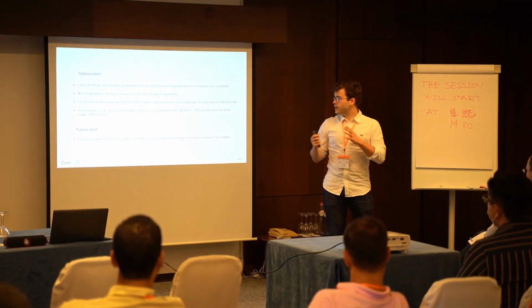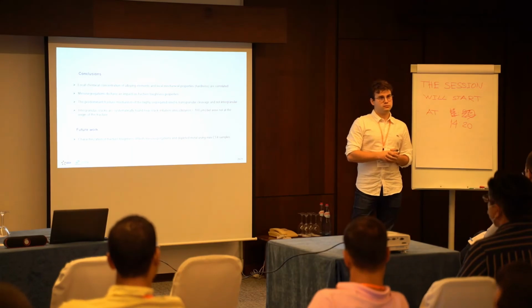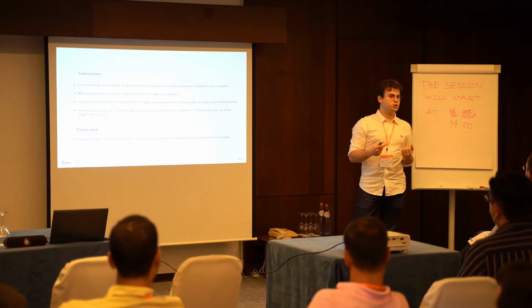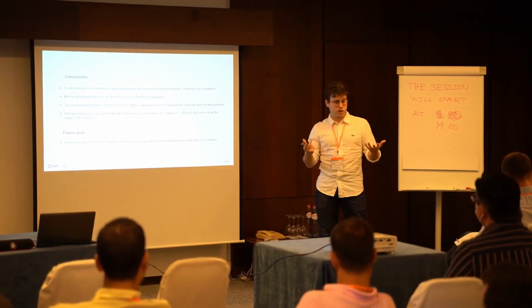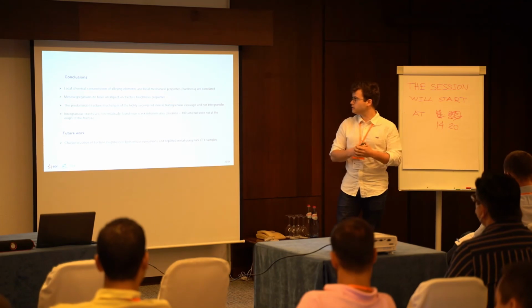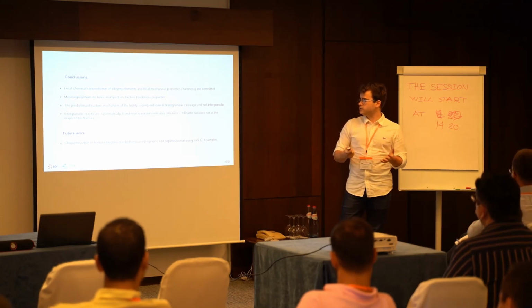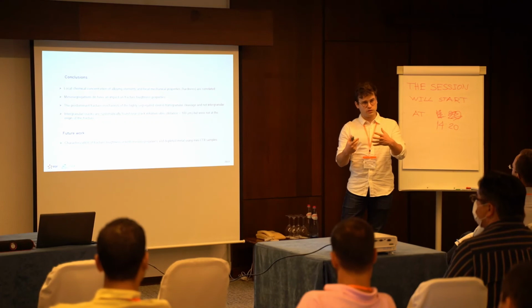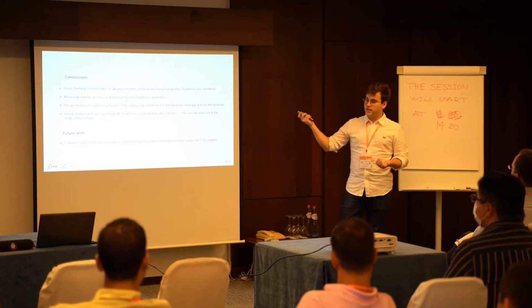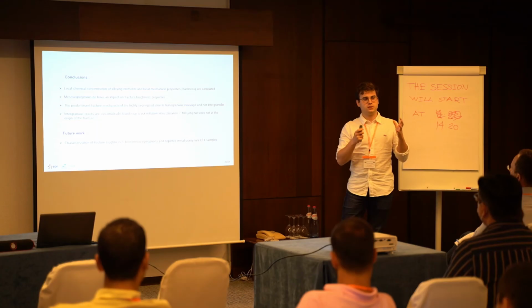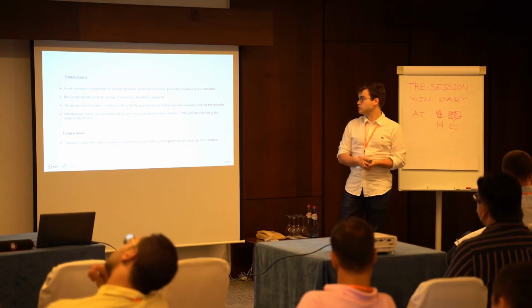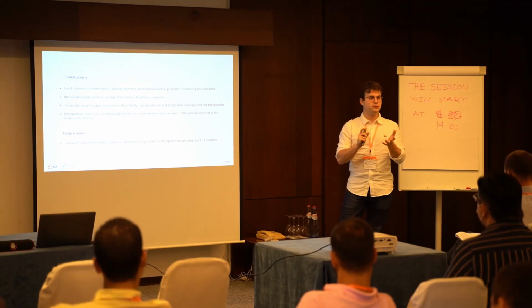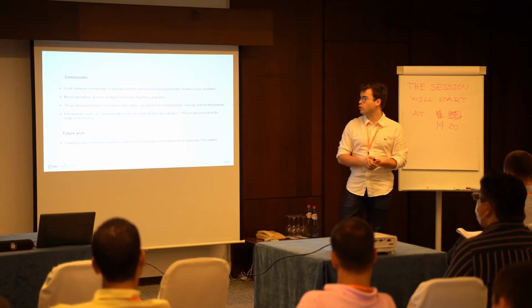To conclude, we saw that local enrichments in chemical composition were very well correlated with local mechanical properties because of the different local microstructure. We saw that meso-segregations do have an impact on fracture toughness properties, but that the predominant fracture mechanism is transgranular cleavage even in highly segregated materials, despite the fact that we systematically found intergranular cracks more or less far from the initiation site.